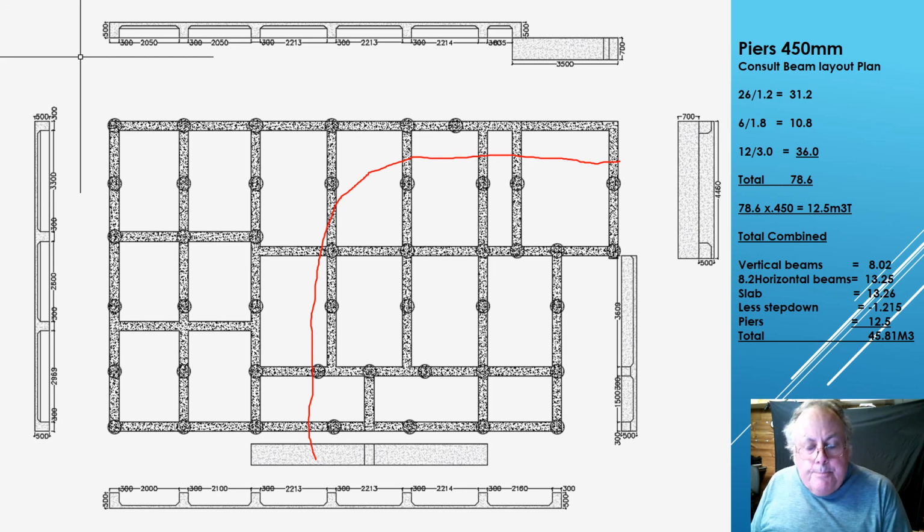And so we need to make it simple for ourselves. And so if we've already worked out our lengths, then it should be quite simple to go through and work out our strip footing beams. So have a go at that once you've finished your concrete, and you will find out many of the dimensions are already here. You just have to choose the right ones.